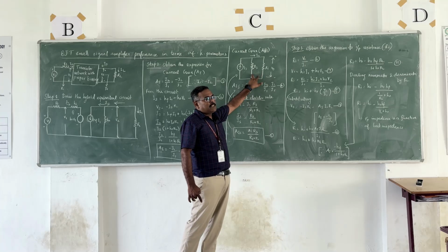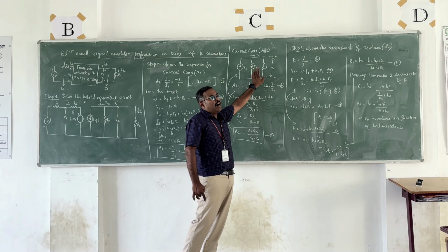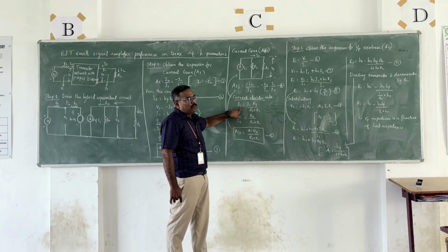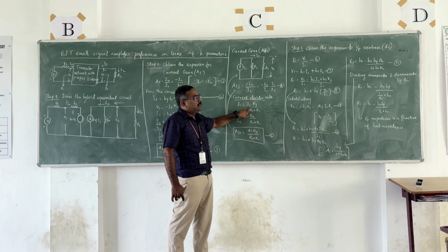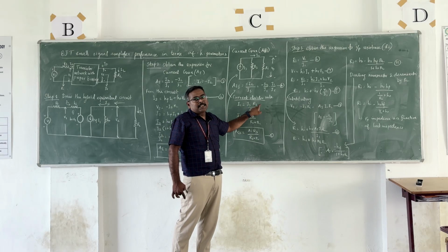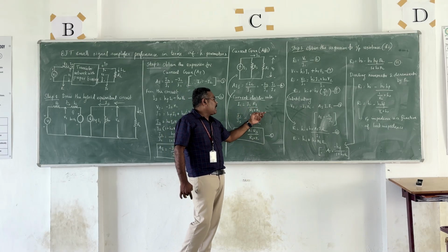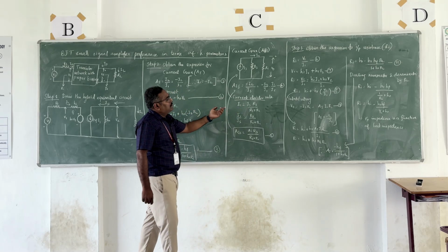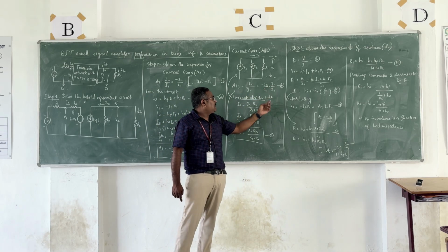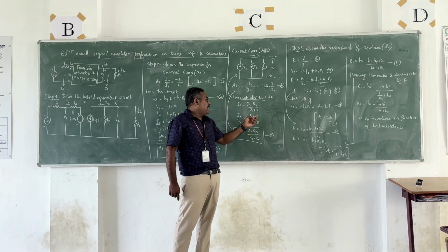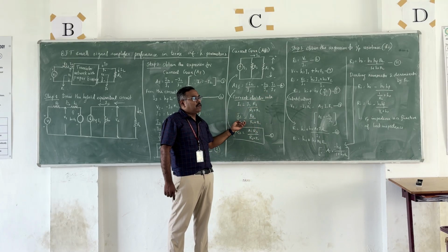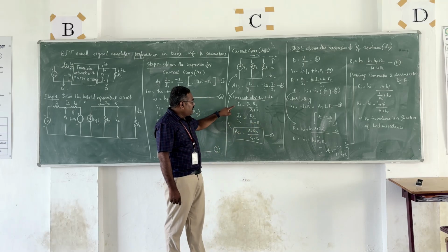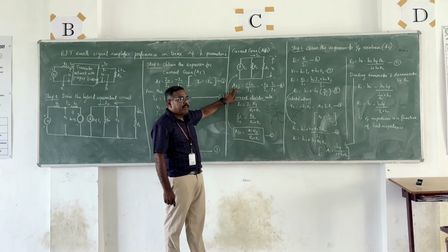The total resistance of this circuit is RS plus RI. So the formula is this, and we have to calculate I1. This is the input current into branch resistance divided by total resistance, RS plus RI. Here we have a rearrangement in the formula, I1 divided by IS. So the IS we move, RS divided by RS plus RI value. This is the equation we need.